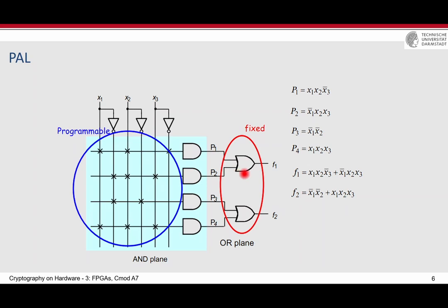And then you may say, if the OR gate has 3 inputs, for example, but I have only 2 terms in my sum of products, how can I implement this, because it has 3 inputs? Then of course the third input should not be connected anywhere. It means that the output of this AND gate should always be 0. Then you can realize it. Or you can say both X1 and X inverted are connected to that AND gate, then definitely the output of that AND gate is 0.